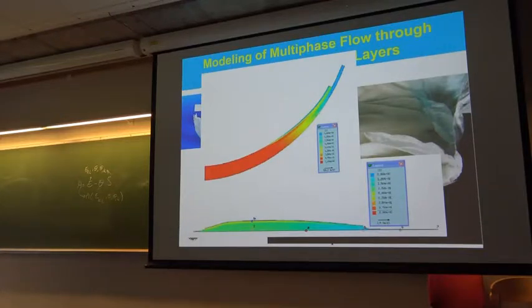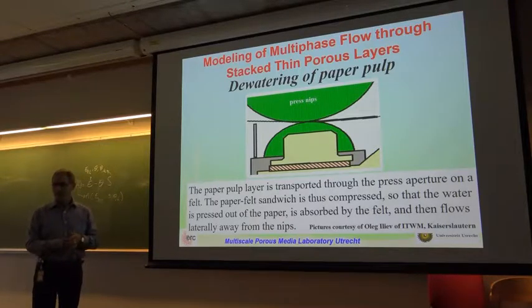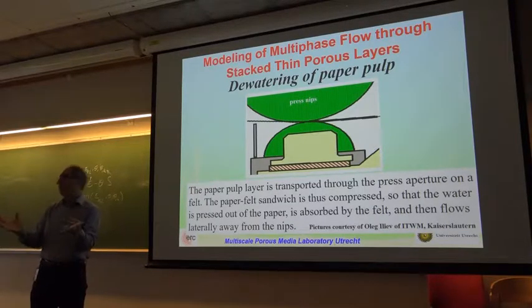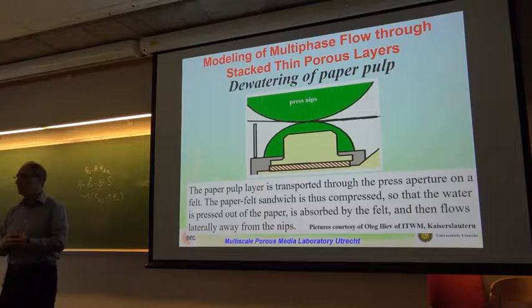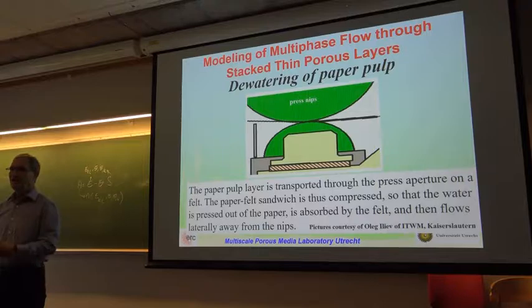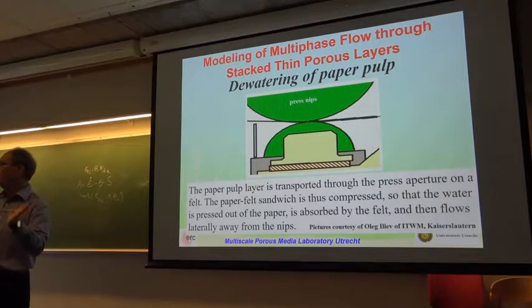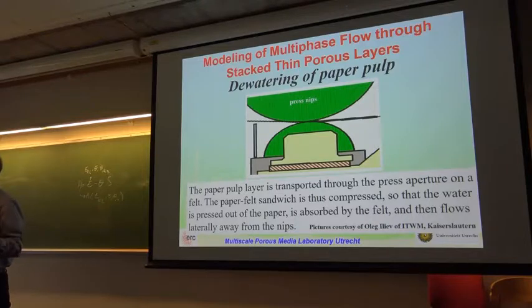And here's another example. In the production of paper, they create this paper pulp, which is more than 90% water. And that water is not willing to leave the pulp to give us dry paper. They can do this with gravity drainage. Okay, that reduces it to 80%, but there's still a huge amount there. At the end, they have to heat it to get rid of the water, but that is very costly.